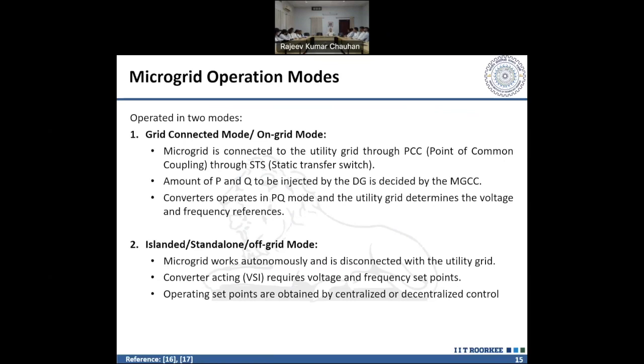In a normal grid there are two very important parameters, voltage and frequency, which change rapidly due to the load. Load may be active or reactive in nature. Normally, due to the reactive power, your voltage will drop. Real power also causes voltage drop, but the major source is the reactive power.